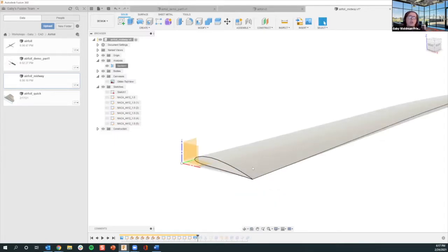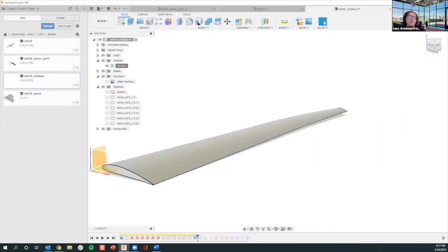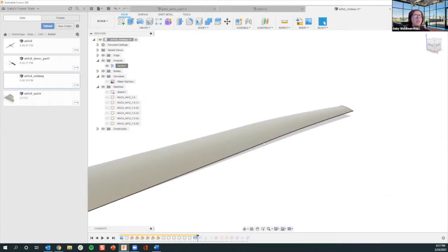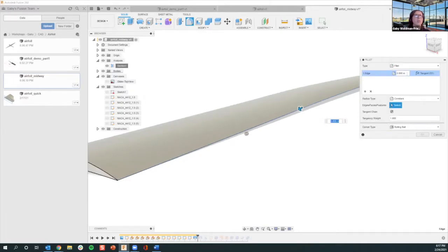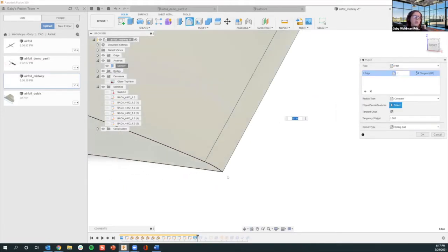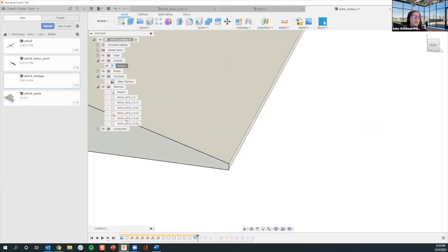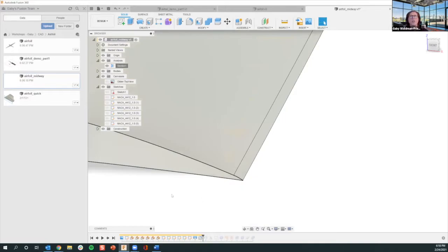And there's really nice things about solids, right? You can come in and maybe you want to fillet this edge. That's too big, it's a small thing. Sorry, let's fillet something else. Okay, that's gonna work. Sometimes it's not able to fillet really small features because it self-intersects. But here's a good example. So, you can add a fillet here. Solids are really good for that. It was a tiny straight edge before, and we added a fillet on that top edge. So that's pretty nice.